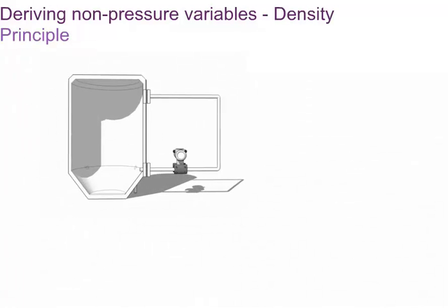The preceding method leads to density measurement in a tank. In this case, a homogeneous liquid of changing density in the tank will exert varying pressure on the transmitter depending on the change in density. This measure can be applied either in open or closed tanks, and with clean or dirty fluids. As long as the level remains above the top tap, and as long as H is constant, the transmitter will respond to changes in density.